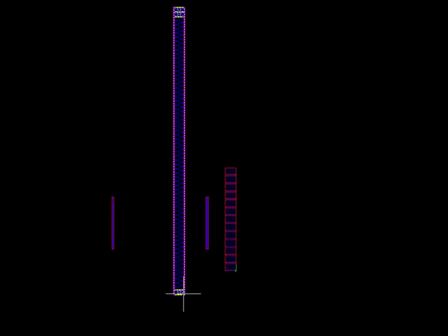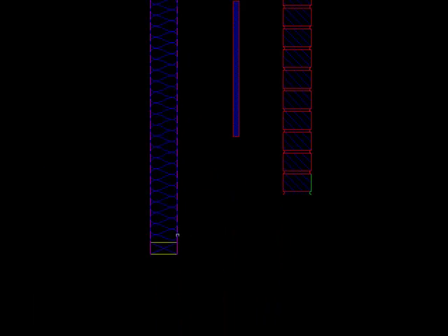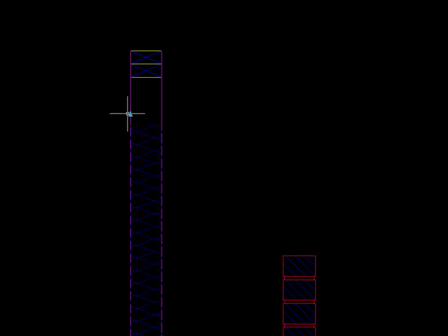I've got a few more over here that I've created. I've got a stud wall. It's got a top plate and a bottom plate and insulation in the middle. If you select it, you see that I have arrows here as well. And I can just drag the insulation and I can drag the stud wall. I have this defined for those to be two different properties because I want my insulation to stop right here short. And I might have some blocking or something in this wall that I want to add, but it allows me to modify them individually.